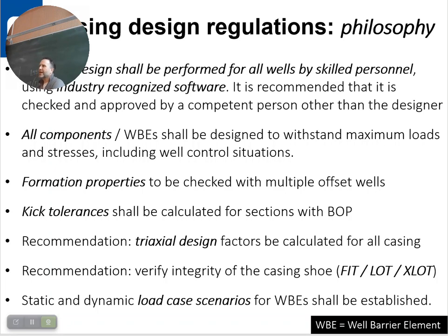And kick tolerance again is a little bit, let me put it weird, how the industry is doing it. Because you only make a snapshot, right? Whereas the kick tolerance is a snapshot for every millimeter or every inch that you drill. Actually, there's a new snapshot, right? Whereas what you do, and what is the practice, is that you check it at TD, right?